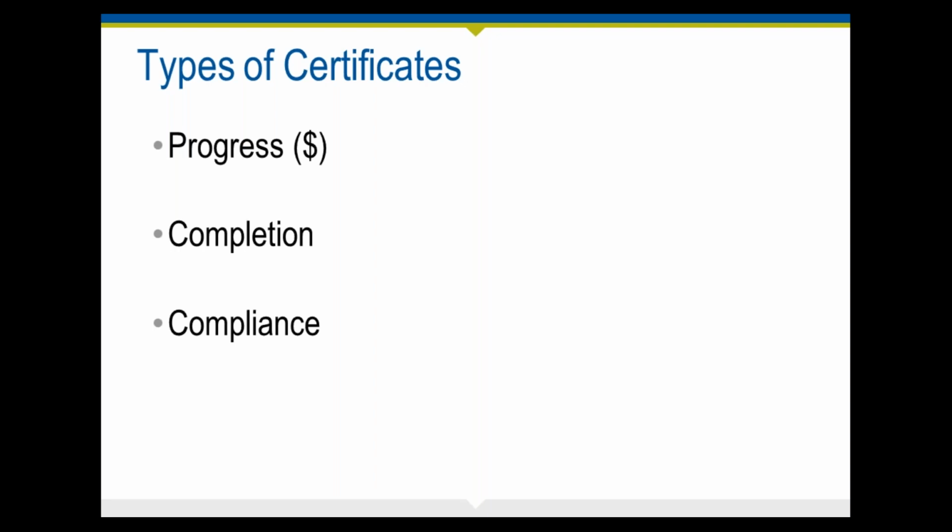Completion is a big issue. Substantial completion dates are very important to the owner, and that is a term of art in the industry. It tells somebody the date by which a stage or designated portion of a construction project is sufficiently complete in accordance with the contract for the owner to occupy and or utilize for its intended use. That's kind of the definition that the standard form documents like the AIA and EJCDC use, so that the owner can start using the facility without undue interference. So from that point on, they can start using the facility. There may be some minor punch list items that you're still resolving, but in terms of the use of the facility, that has been turned over to the owner.